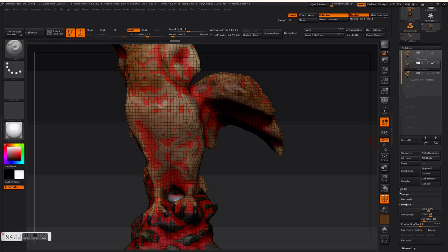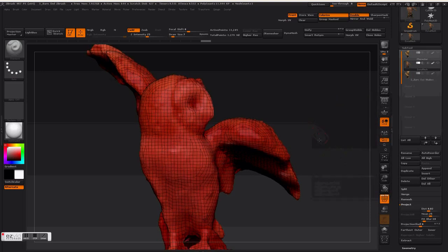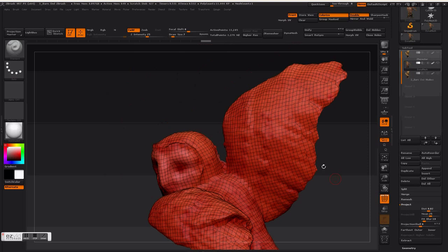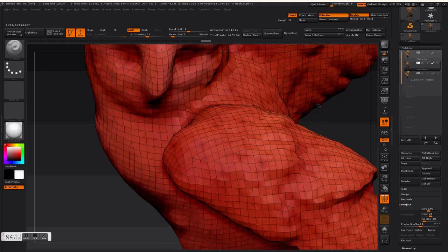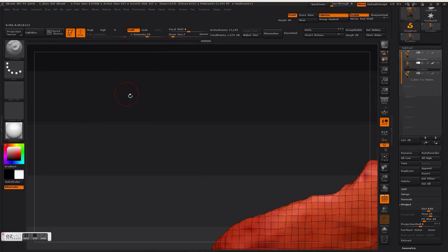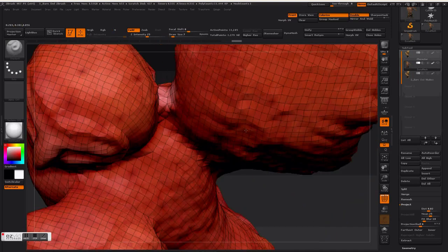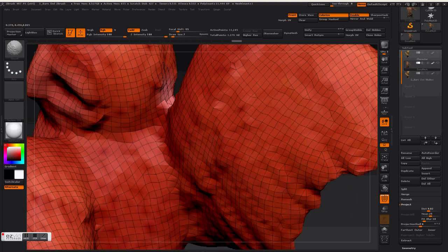And yeah, firstly just project the low polygon mesh onto the high poly mesh. So just press project all. So that seems to have worked, I think. And you still have to be careful to not get these errors being pushed in with the project all button.